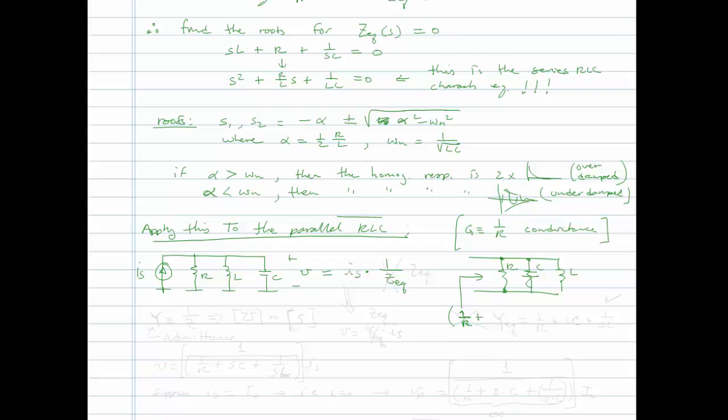Well, in impedance, we have something similar. We define admittance. It still sounds like conductance. It admits current flow. Admittance is defined as 1 over impedance, and it's the letter Y that we use. It has units of mhos, or Siemens. And you recall when we combine resistances in parallel, we can more easily just add their conductances and then take the inverse afterwards. So let me rewrite this.